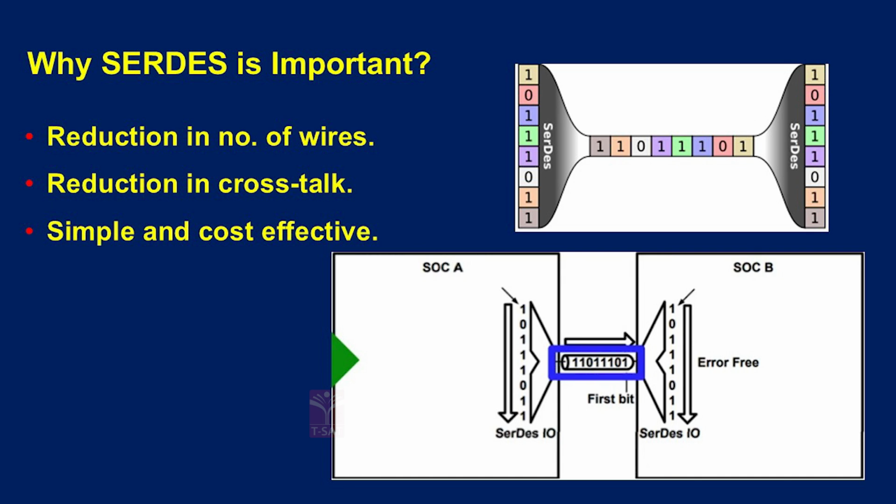So, here you have, let us say, a total of 10 bits or 8 bits, right. These 8 bits, if they are going at, let us say, a 1 gigahertz rate, this particular channel should actually be running at 8 gigahertz, right. Then we have to look at whether this channel is capable of doing it. If not, what do we have to do, what do we have to make sure to address? That is one thing which we generally take care of before and after the data transfer, right.